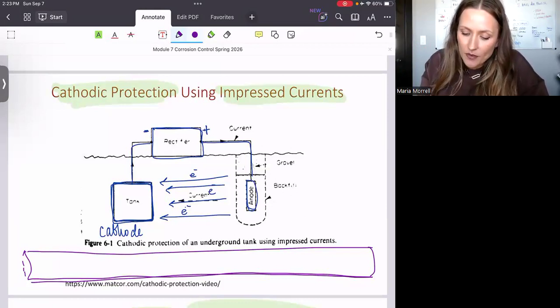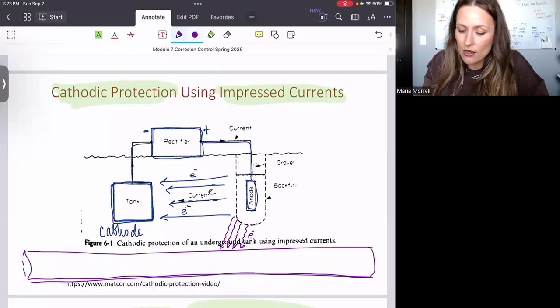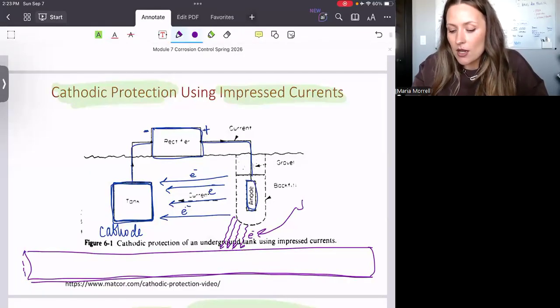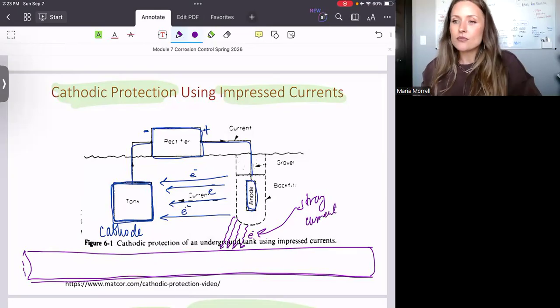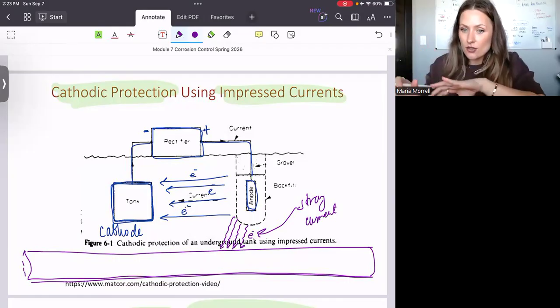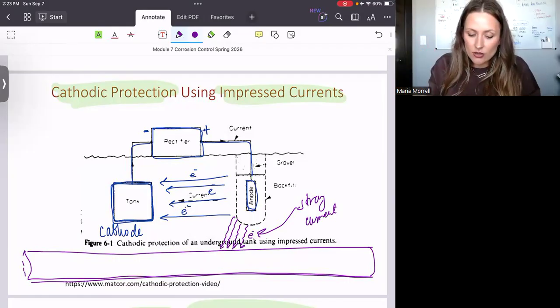But instead, imagine that there are a few electrons leaking through here, okay? And I'm going to give it a name, stray current. Very dangerous. And because there is this metallic pipe, it's going to conduct this stray current and eventually it's going to leave the structure toward my tank.